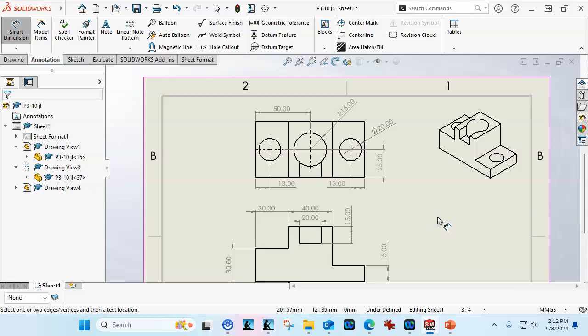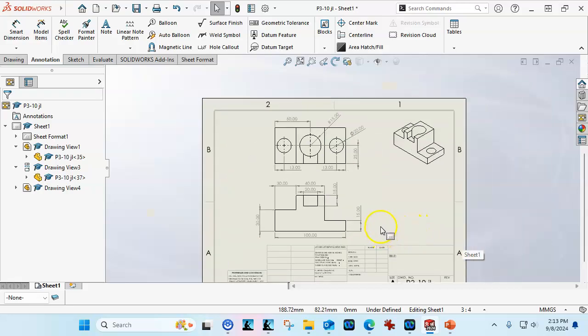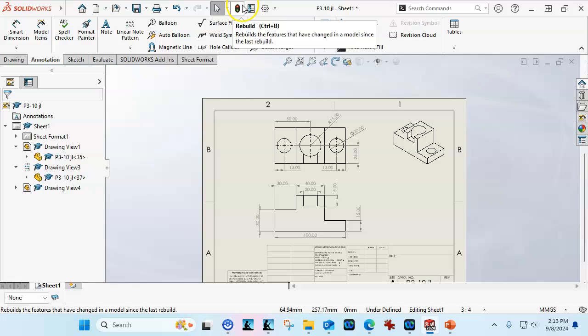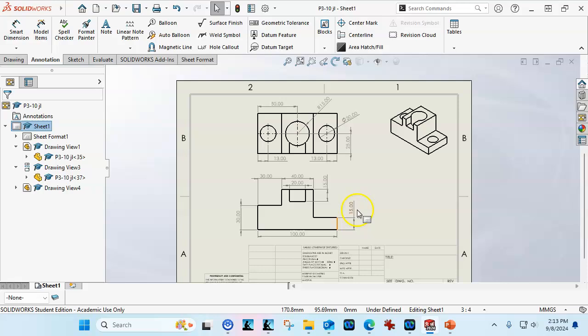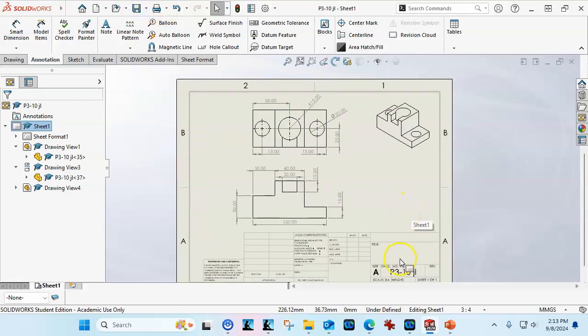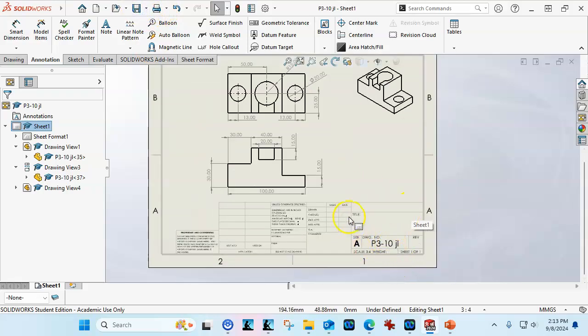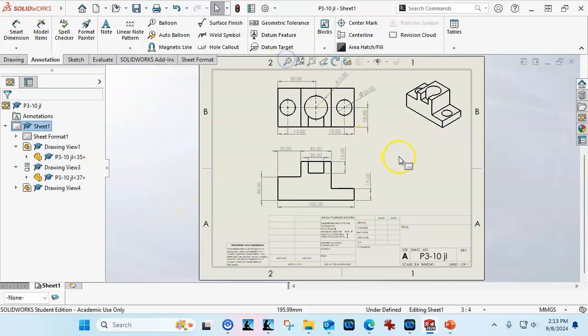The other thing that I wanted to close with then is the ghost lines that control. Let's see if it has the Control B for the rebuild. There's also a Control Q which forces a complete rebuild, and the Control Q actually removes the ghost lines. So I'm not worried about the titles. Doesn't look like it brought anything more than the drawing number, so that's good enough for now. And I think we're good on this drawing.